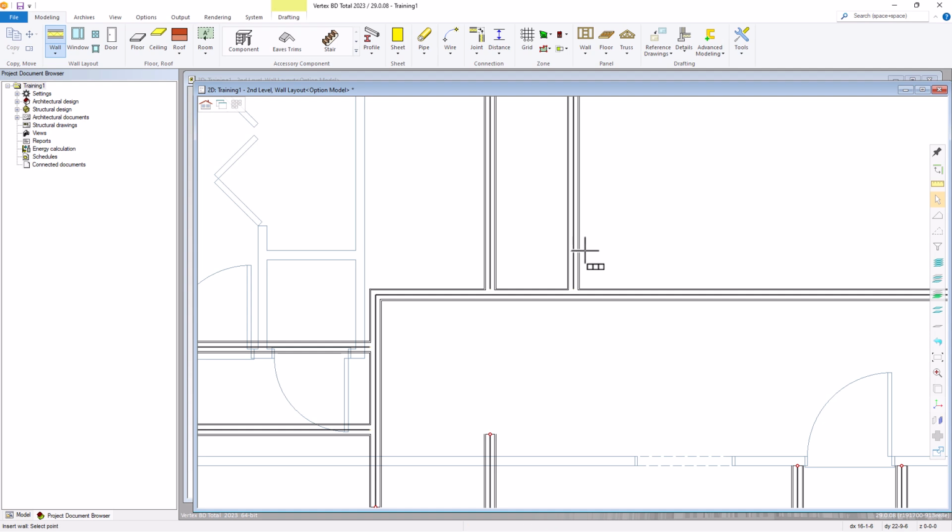V to confirm. And we have another closet, which is 2 foot 4 off this wall. So we'll hit Q, lock it in the vertical, type in 2 foot 4, hit the letter U. That wall is offset towards the top, which is correct. And we'll just butt up against that wall.